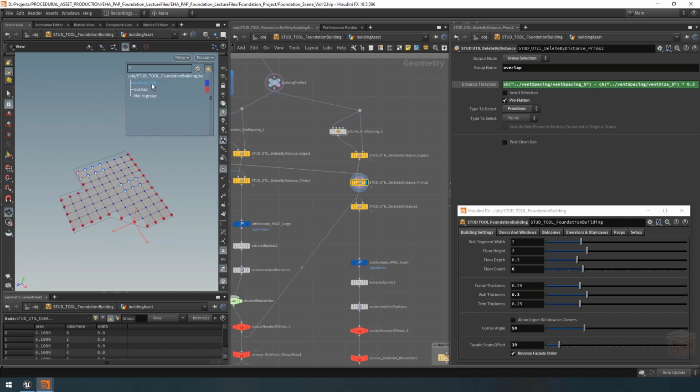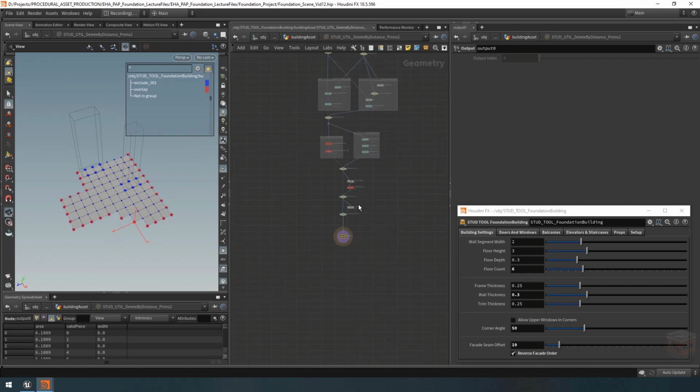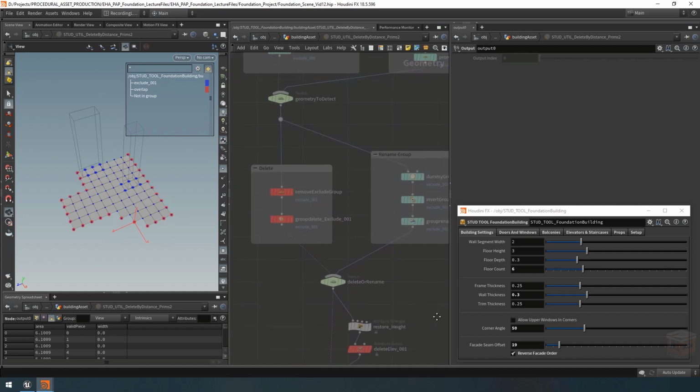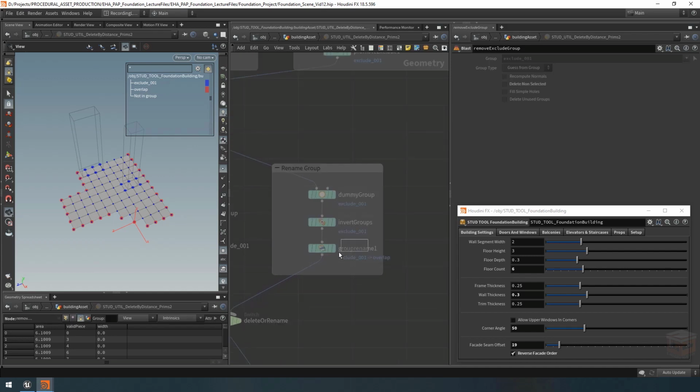then now instead of merging our previous group and our selection of points, it's creating a new group here called exclude 001. And that's actually the group inside of this node that we were using to carry our selection throughout this node, and that's a bug. We don't want this to be exposed outside of the node. This is a group exclusively for the interior of this node, and we normally go and throw it away, but we're only throwing it away when we're actually deleting our points. And on the right, we were trying to rename it to overlap, but because in this case we have this bugged out situation, this is breaking and we need to fix that.